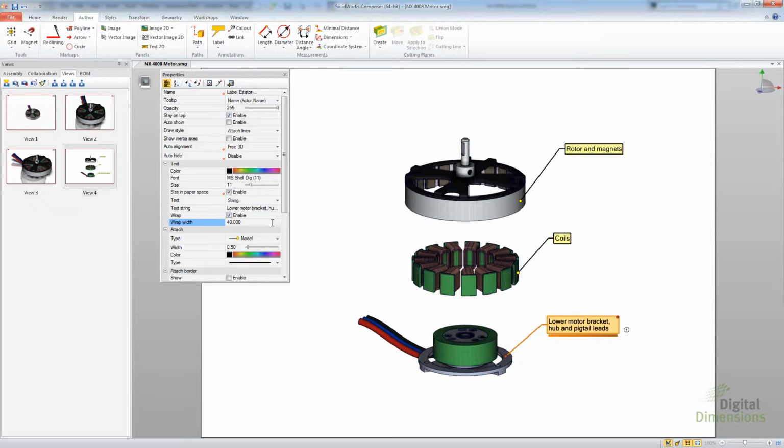Alright, next option here is the auto hide annotation when anchor is hidden. Okay, so what does that mean? It gives us an extra auto hide. There are 3 different options. There's a disable, there's a standard and there's an advanced. They do mention that the advanced is time consuming, so that option does slow it down. What the advanced one does is it actually allows, if there's an associated item to this particular part, then it'll auto hide with that as well. So standard is kind of the straightforward. Let's go and set it to that one.